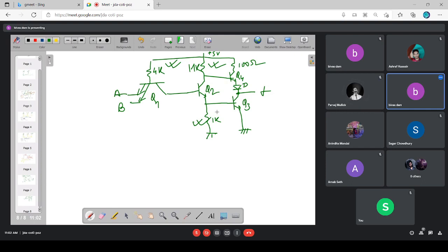Yes, sir. But what problem will you be facing in turn? The delay will increase in turning on and off. The switching time of the device will get hampered.